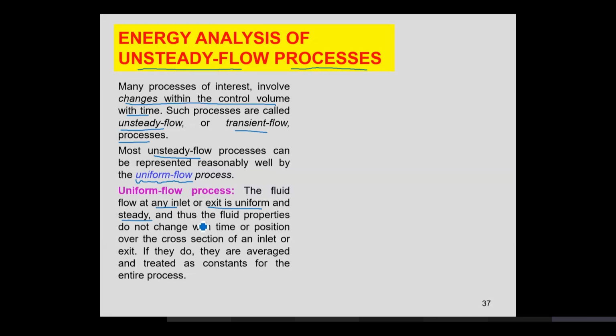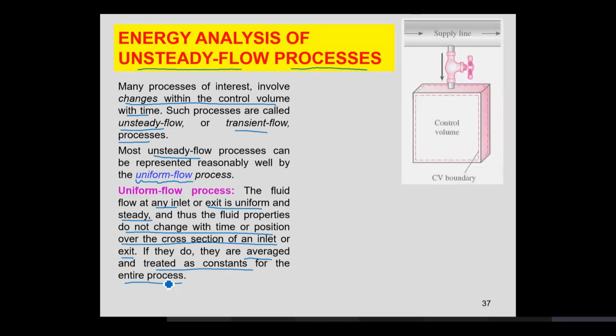The fluid properties do not change with time or position over the cross section of an inlet or exit. Even if they do, you take an average value for the time and position, and they are assumed as constant for the entire process. However, within the control volume, the properties may change with time. So this is the specific case of unsteady flow process.